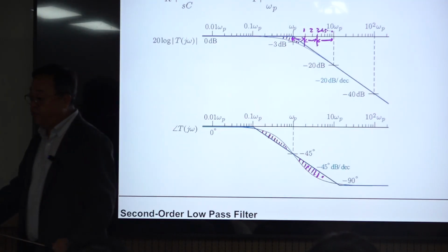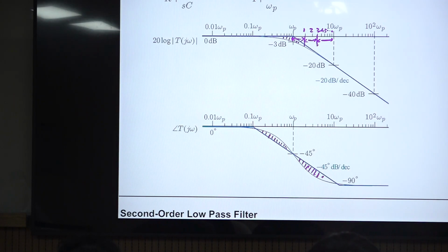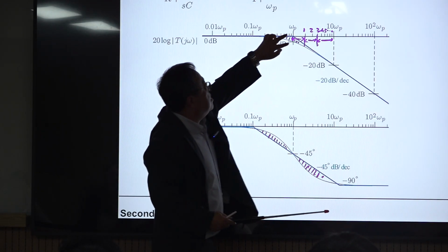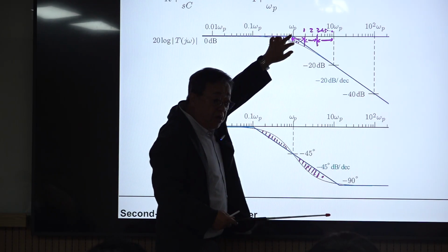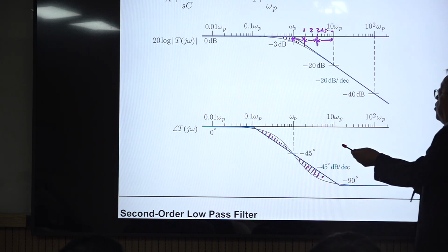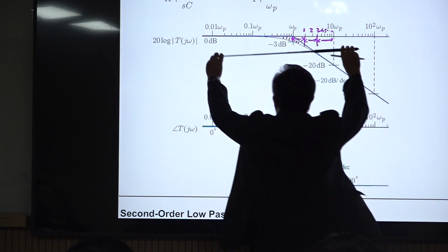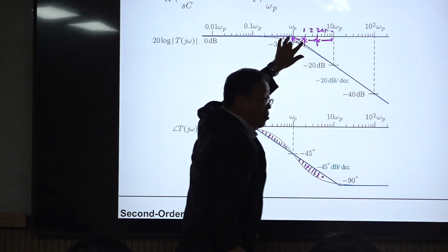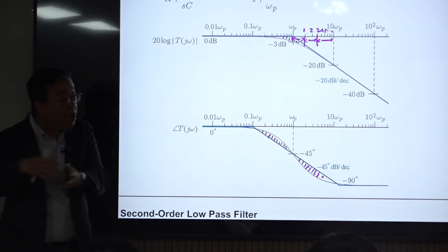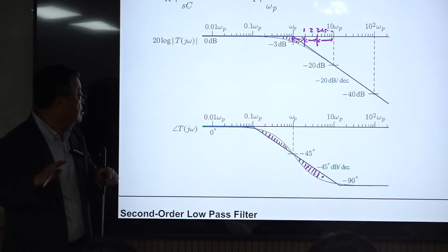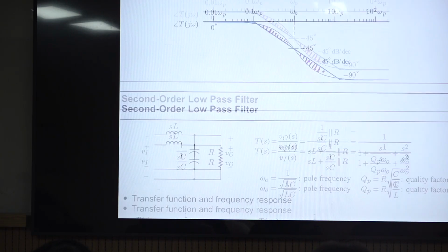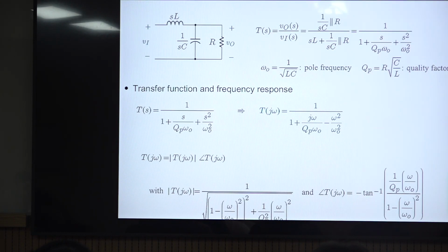It's called low pass filter. So this is low pass filter, and this frequency, where there is a 3 dB down here, or a 3 dB error, is called 3 dB frequency, and also called corner frequency, because this has a corner, okay, and pole frequency, breakover frequency. They mean the same thing, okay, same meaning. You are using different terminology. They are the same thing, okay.